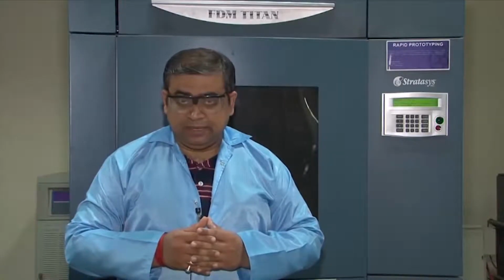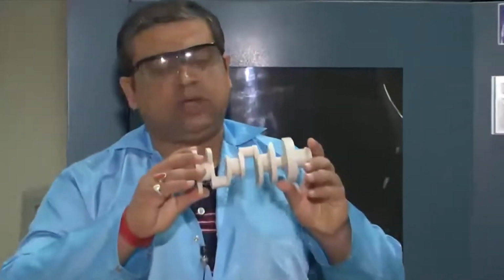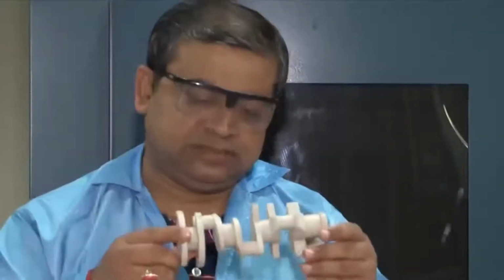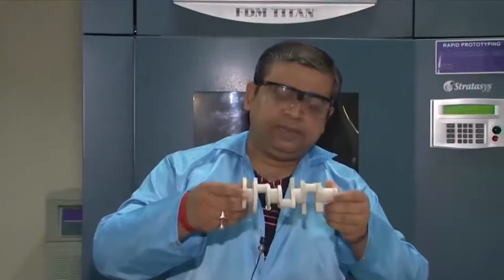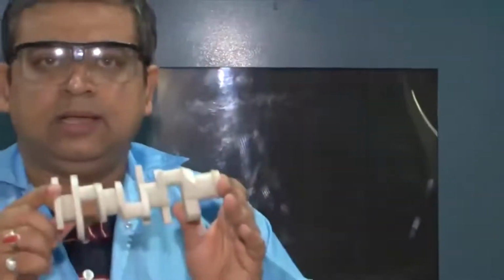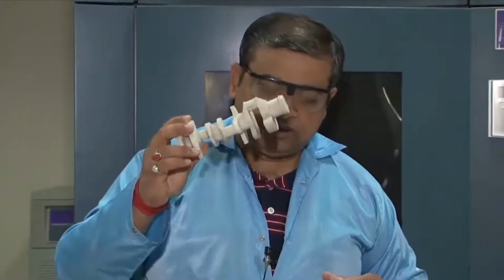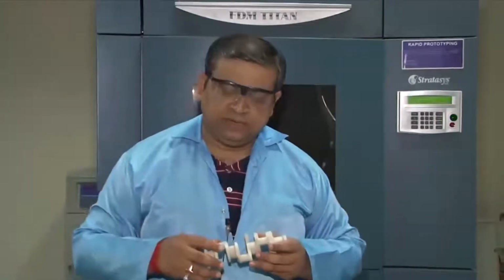Okay. And in a way what happens is that once your CAD file is designed, irrespective of whatever is the complication which is involved, I'll just show you, for example, what I mean by complication. Okay, this is a crankshaft, okay, of an automotive. You can see the design and you can look into the kind of complexity which is involved in designing such a part. Typically this is used in the automotive industry, and the way you generate it is in forming processes. But here you're basically depositing and making a scaled prototype or a model through which you can probably formulate the next step, okay, which can be used for die manufacturing for that forming process to happen. Okay. So one advantage of this kind of a process is because of the complexity of the shapes it can handle, it can be used as an intermediary for some of the primary manufacturing processes also.